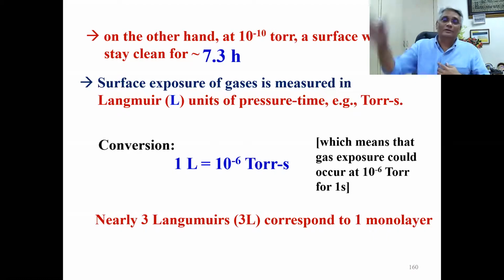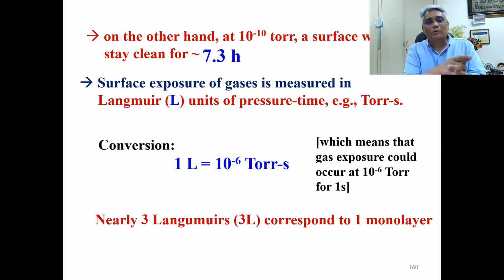Okay. So this example clearly demonstrates how important vacuum is, not only from the point of getting good quality thin films. Now you see, if I use the substrate which I think I have cleaned, but I have not bothered about keeping it in vacuum before the deposition is started, I am depositing these atoms on an already contaminated surface.